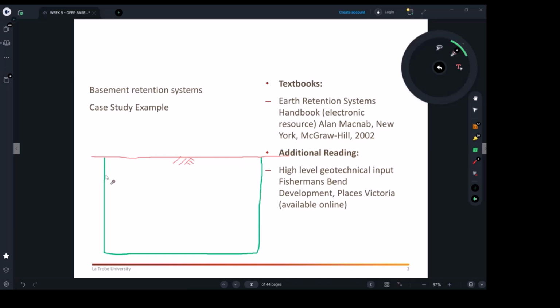So what we do here, before we excavate, we have to build a retention system. That's where it's coming from. You want to retain the soil until you actually build your hole or your basement, and then start putting your slab, putting the columns, definitely footings, columns, the other slab, another column. That's really how it's working.